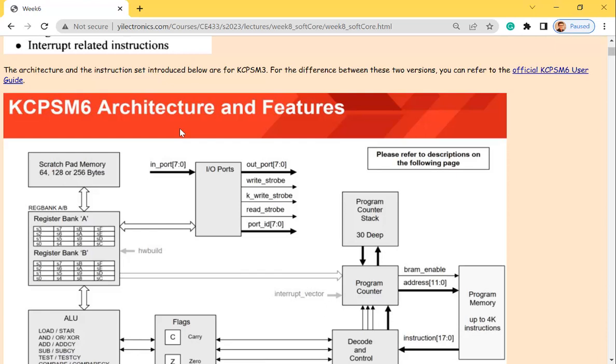But you can still program the FPGA using Verilog because they also have all these other lookup tables for you guys to program and synthesize. So you can make the connections and design peripherals for that CPU. For example, you want to write an SPI or I2C port. It's a digital block, and you can do it in Verilog and synthesize it and make it into an IP block with all the pins, and eventually make the connection in your Verilog to the core.